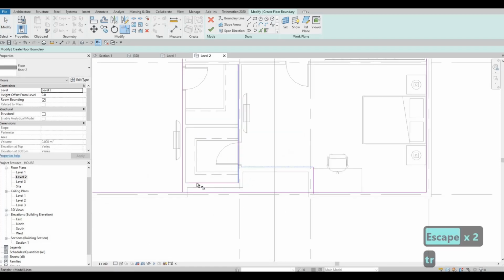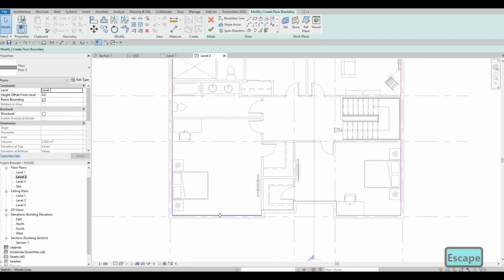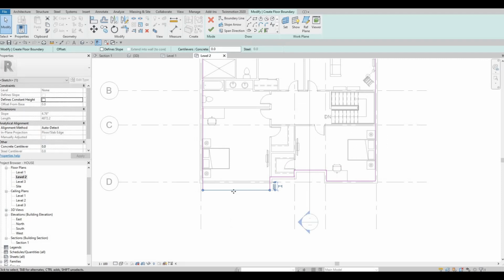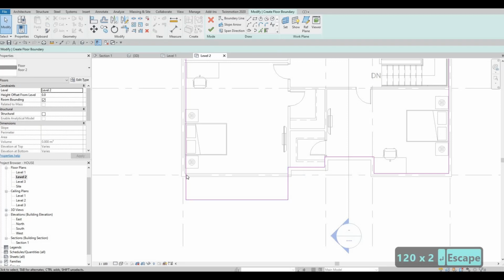and then let's use trim, and then here we need to type in SL, so trim and X, so that's split, and then TR. Let's trim this. Like I said, I'm going to extend this a bit, and I will reference the one below. So around 1200, I believe, is what I said. The extension of our